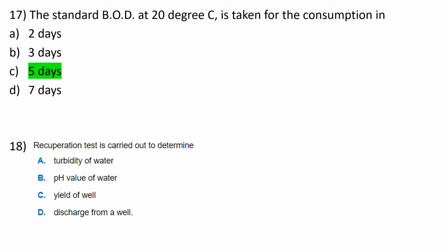Question number 17. The standard B.O.D at 20 degrees Celsius is taken for the consumption in A, 2 days, B, 3 days, C, 5 days, and D, 7 days. So the answer is 5 days. So the standard B.O.D test at 20 degrees Celsius is done for 5 days.